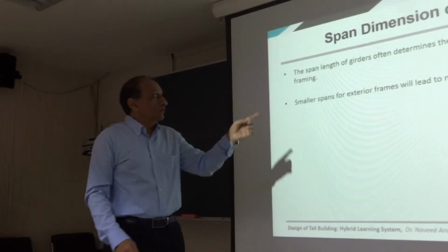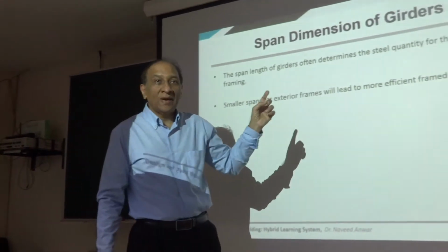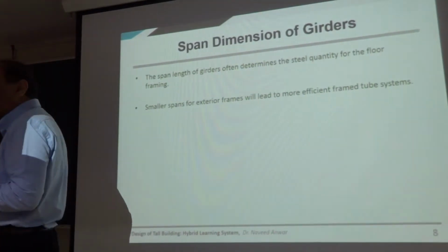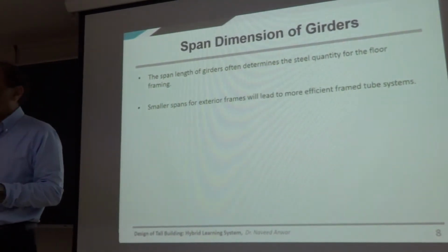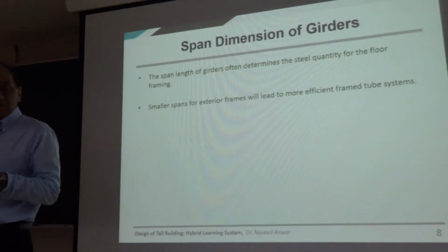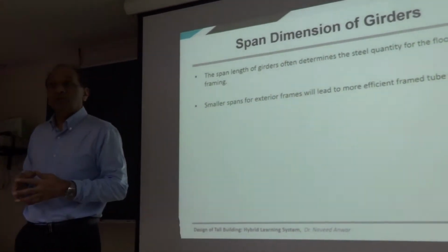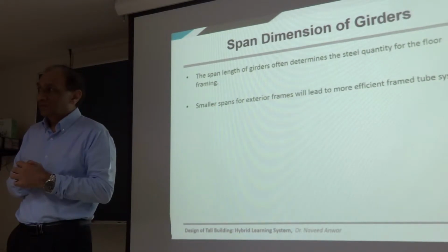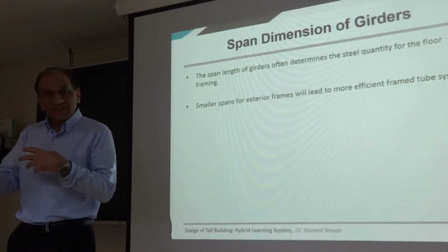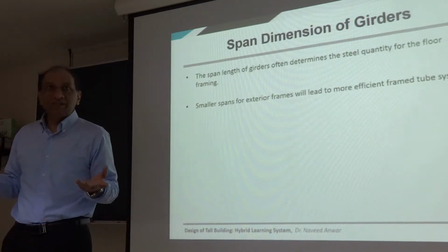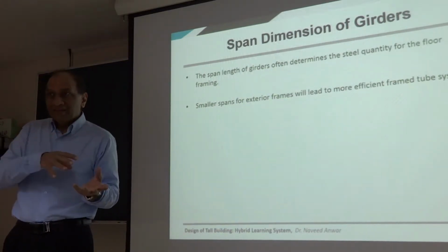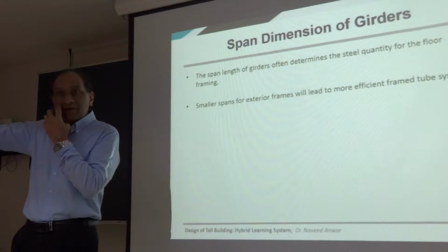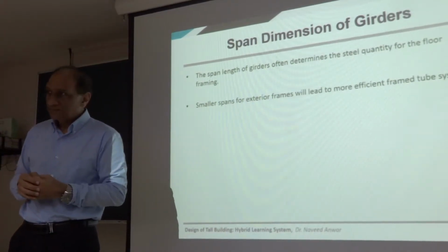So that means you need to find a flooring system which can span 10, 11 meters, 10 is typical, up to 12. 12 meters is quite a lot of space, right? So you need to find a system which will be suitable for 12 meters. That's where post tensioning comes in, because it helps you to span longer spans. So you have challenges on the floor system because the spacing of the column is too big, and you have challenges then on column size because they want the minimum column size. They only want the columns outside the building, not inside, right?